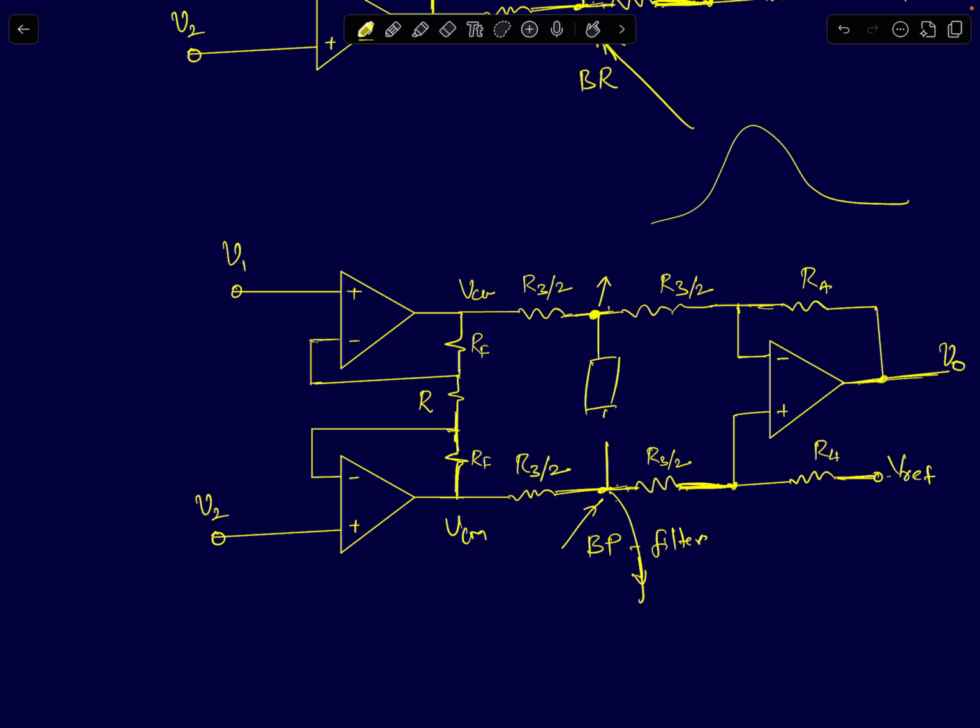So you can add some impedance network here between these two pins and get the desired filtering you want for differential inputs. So it may turn out your input differential signal has some unwanted components. It has some supply noise over some frequencies or some additional noise you want to reject. Then you can put some filter impedance between these two nodes and reject them. Common mode noise, by default the circuit is a differential circuit. The second stage is a differential to single ended converter. That will anyways reject all common mode noises, ideally for all frequencies.